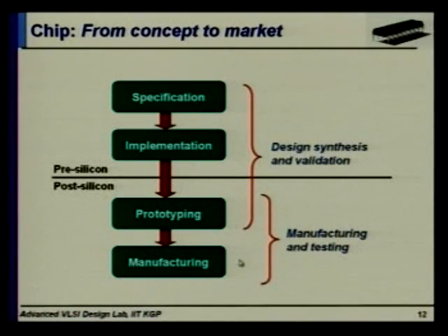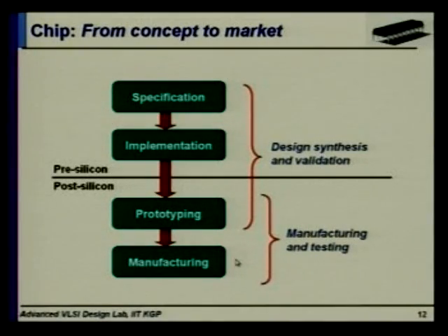The manufacturing test cannot be that thorough because you cannot spend an hour on every chip when you have to tape out 50 million chips. Then you are not in the market anymore. So you have to judiciously decide exactly what has to be tested within the time limit, so that you can make sure that there are no manufacturing defects in the chips that you are shipping out.